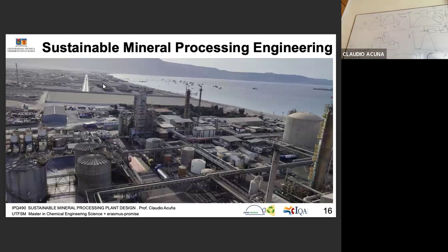Another case, this is the sulfuric acid plant on the top of the prilling tower. A prill, for example: you have a solution and you generate a drop. It's a very tall tower, and as the drop goes down and you put in hot air, it evaporates and produces a crystal. This is a prill generated from solution. And you will see, actually, we touch it. I don't have the video, but this is the size of the prill.